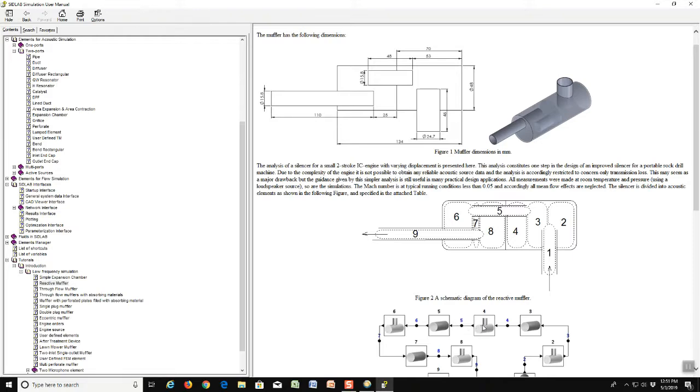Also, number 4 is a quarter wave resonator, and its length is the distance from the transfer tube end to the baffle in the middle. So actually, it is modeling this, not the tube itself, the transfer tube itself, but the space around it. So this is something that will become more evident and obvious as you use SIDLAB, but at first it is not obvious how to apply the quarter wave resonators, but this is an example of one way that it's done.